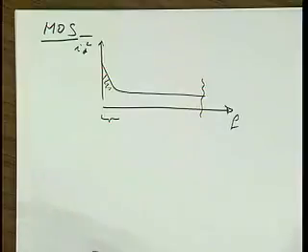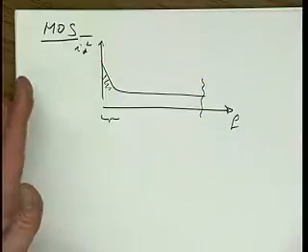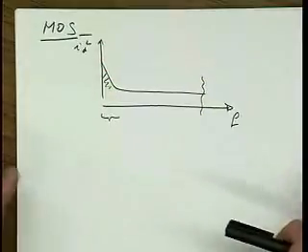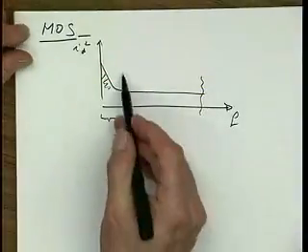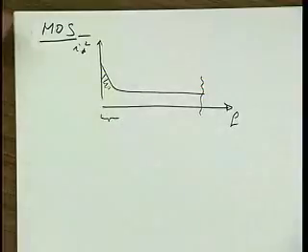In nonlinear circuits, a little bit different, right? In an oscillator or so, sometimes the flicker noise can be upconverted to the carrier. So then it's important. The other thing that is special about flicker noise is that because it really occurs only in a particular frequency band, there are a number of tricks that have been invented that allow us to actually attenuate flicker noise to the point where it becomes irrelevant.